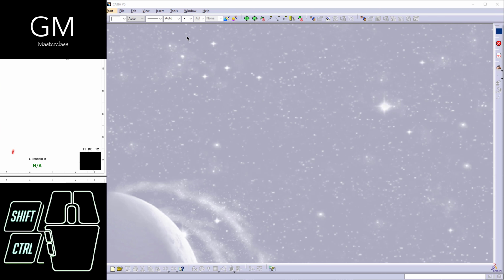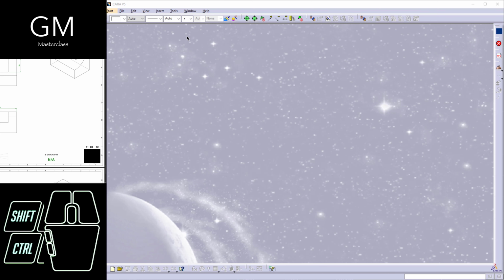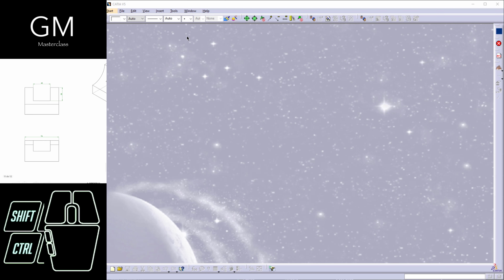There is usually a box right here or whatever, taking into account the normativity of the technical draw, that contains not only the unit system but also the material, the person who did this engineering draw, the person who checked the engineering draw, and more information maybe about tolerances, the material or that kind of information. But since there is none, I can assume that these are millimeters, right?